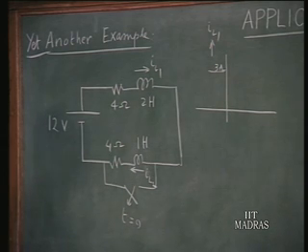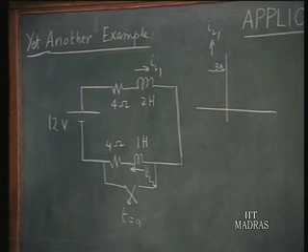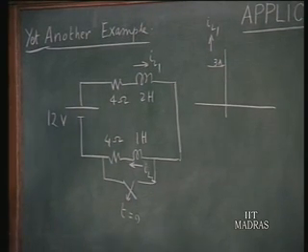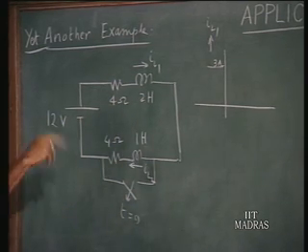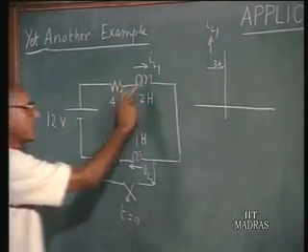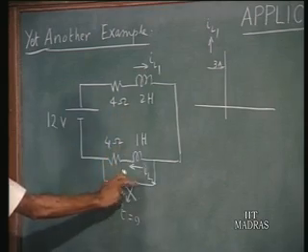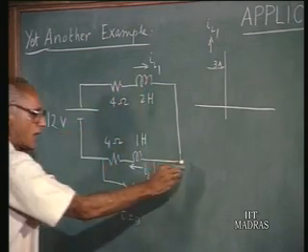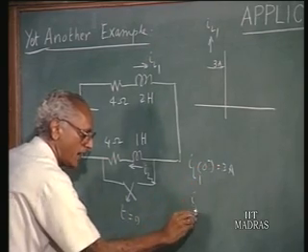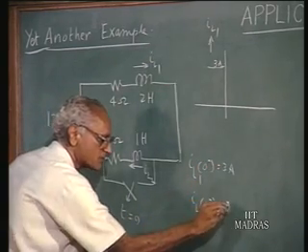In the differential equation approach, we calculated the t equals 0 plus conditions separately. Now let us use the Laplace transform method and show that once you substitute t equals 0 minus conditions, the 0 plus conditions almost immediately follow; in the normal routine you do not have to make separate calculations. So let us use 0 minus conditions and solve for this circuit. You recall that when the switch was closed, IL1 at 0 minus is 3 amperes and IL2 at 0 minus was 0 amperes.